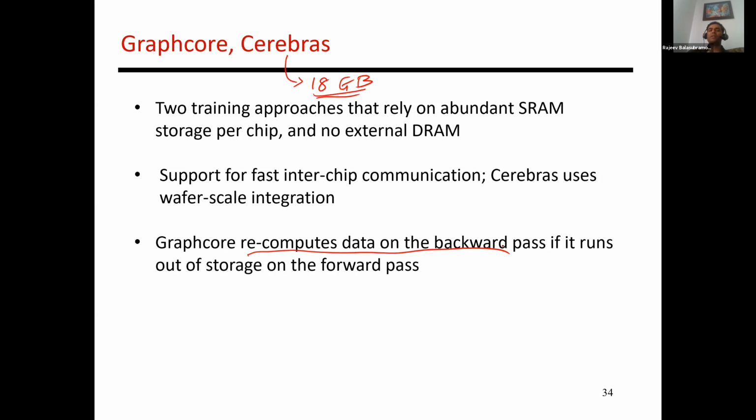The other key innovation with Cerebras is it uses what is called wafer scale integration. Right, so once you've created an entire wafer of chips, they're not actually breaking it up. They're essentially using metal layers to implement the communication between those chips, and they're keeping that wafer intact. Right, so all kinds of engineering issues with that, but that's their main investment, and that's their key innovation to say that I'm just going to give you an entire wafer